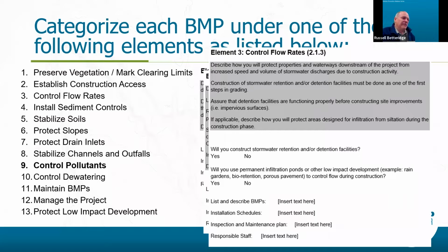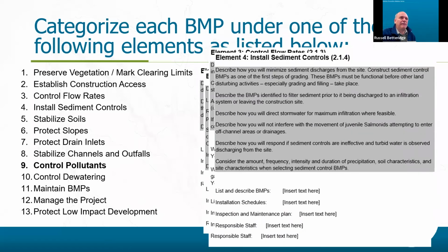You know, and then listing and describing your BMPs. Don't shortcut yourself. Don't limit yourself to just one. Oh, we always use this and it's always worked in the past. You might have to think outside the box because you've got a new site. Install sediment controls. You know, I love it when I show up on a site and the only thing they're using is sediment socks and they're washing everything through it, paint, drywall, all of it's going. And they just point to the sock and say, hey, look, we've got our sediment sock, but that's only for filtering sediment. There's a ton of other BMPs you have to consider. You can't just use one sediment control for all the pollutants on your site.